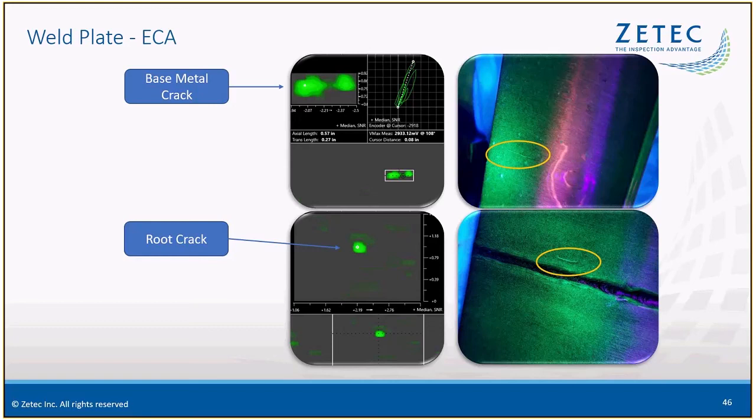If you have that level of information, you can do additional analysis on the indications. And so what you can do is go to a particular point where there's a peak or the worst case area, and look at the voltage and phase in that area.